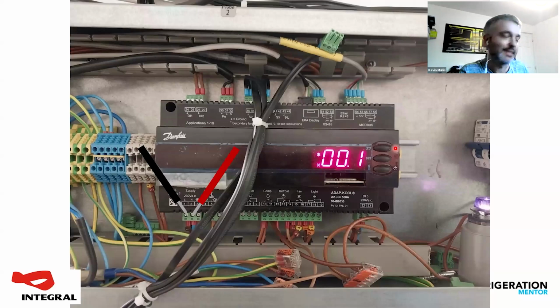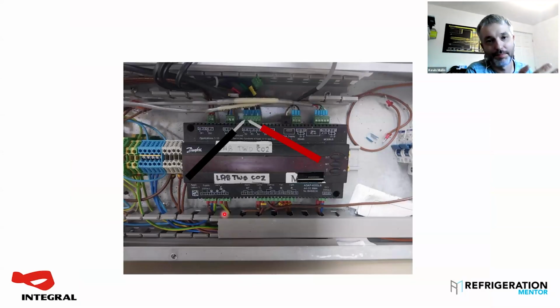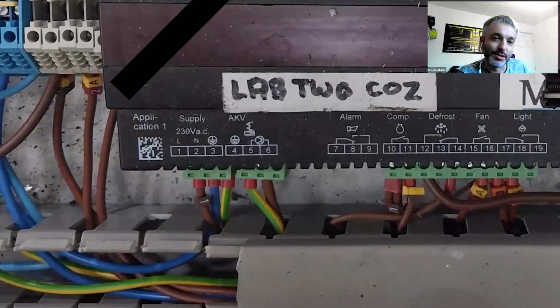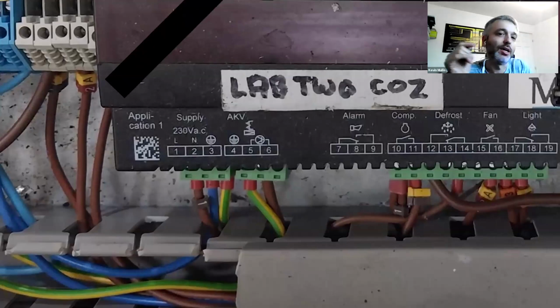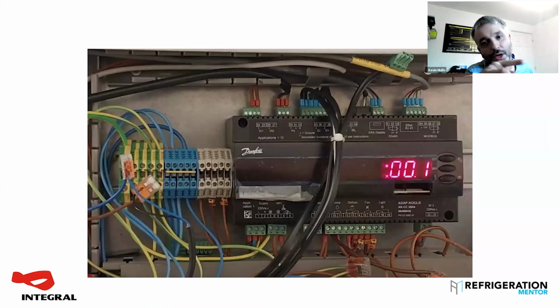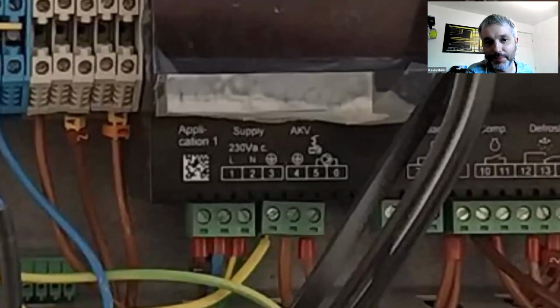Assuming it's running, but let's say for some reason it's not cooling, hidden underneath those probe wires there is the plug for the AKV, which is obviously Danfoss's expansion valve. There we go. So as I said, difference to the old Danfoss controllers, all this is doing is taking the line voltage and switching it on and off through a big transistor. So you're going to want to check that you've got a voltage going into that and that you've got a pulse coming out of it. It's going to be terminals 5 and 6 there. So that's going to be your supply in and then your feed out to your valve. So you're not going to see permanent voltage on the output of that.